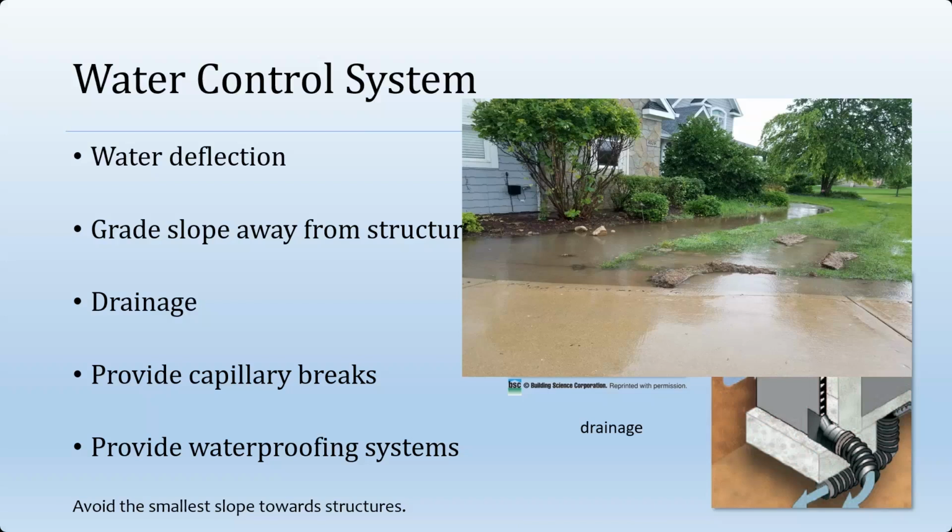And they ran it underneath the front elbow, the bend in the front walk, about 4 feet off of the walk, about 12 inches below the soil, into a 90-degree thin-walled white PVC elbow with one of those friction-fitted slotted ends in, thinking that the heavy clay-packed soil would somehow magically absorb half of 2,500 square feet of rooftop water into the soil. Well, every time it would rain, there would be probably a 12-inch high, 3-foot by 6-foot grass dome that would develop from all the water underneath.